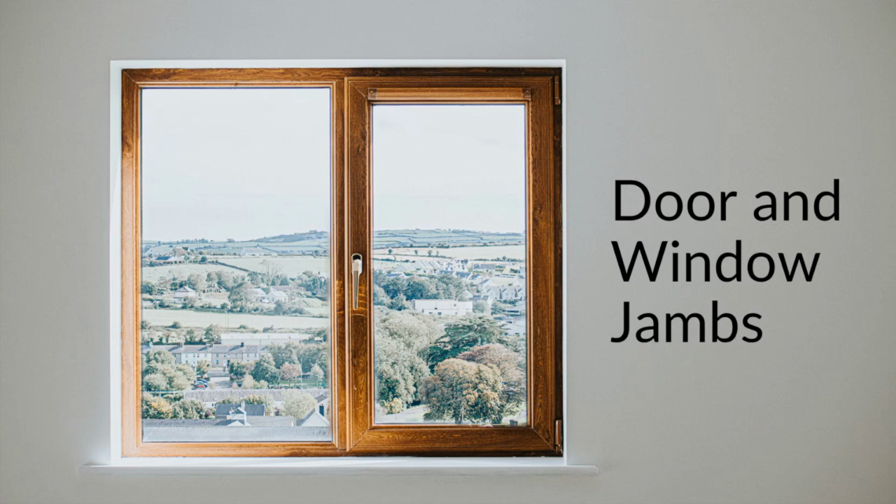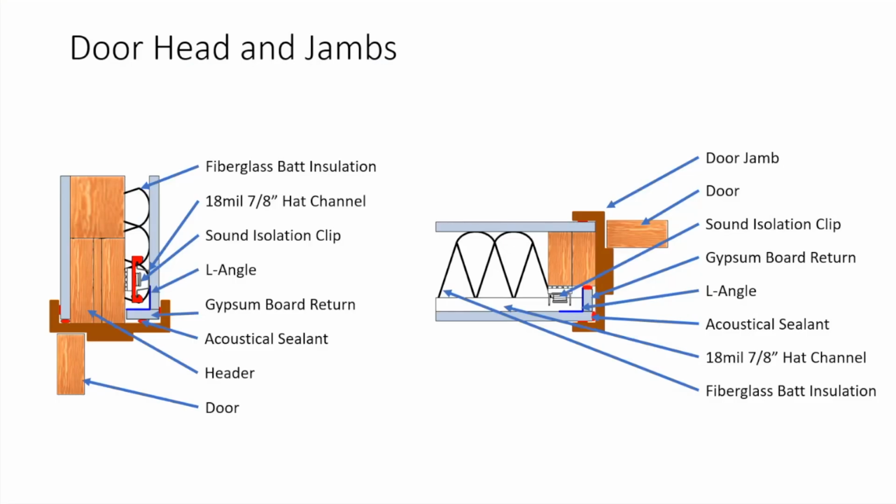Could also be you're designing a SCIF and you've got a door in that, and you've got isolation on your walls, or a recording studio, these kinds of things, right? So how do you handle this detail where you have clips and hat channel that offset your drywall further from your studs? And so when you run into a door jamb, it creates this little gap there. And how do you handle that detail?